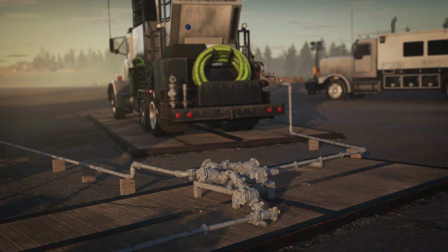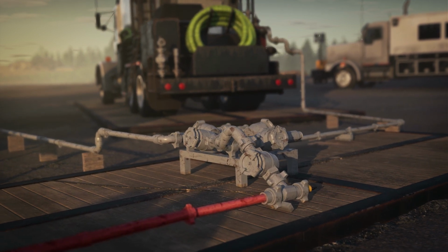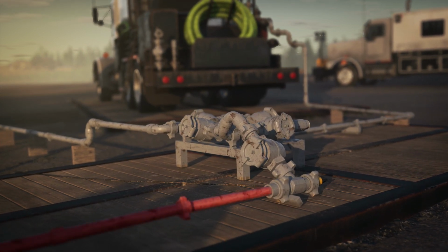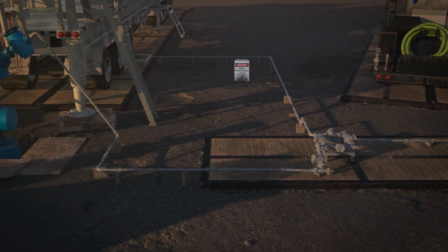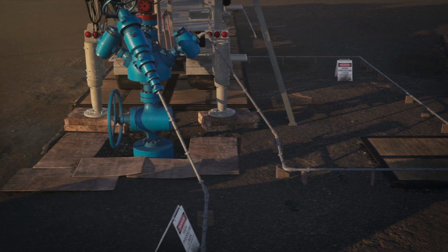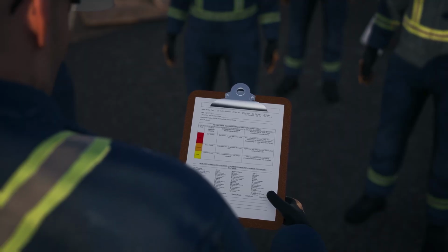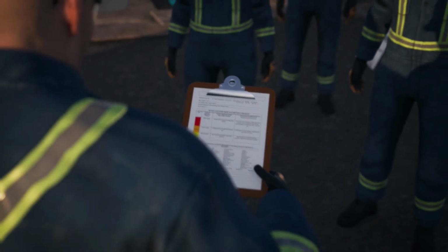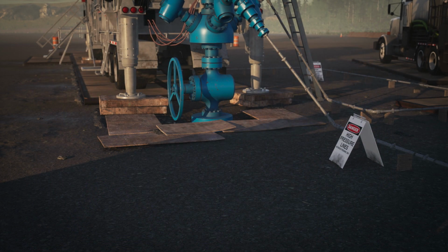3 critical errors occurred during this exchange. The night crew did not depressurize the equipment before the crew change. The day crew did not walk the line, as is typical when transitioning equipment between crews. And finally, the day crew did not conduct a safety meeting, as the plan was for everyone on the site to have one safety meeting when the fracking crew was ready.